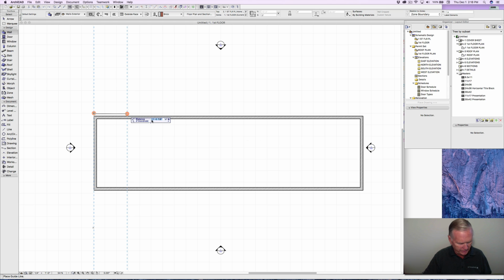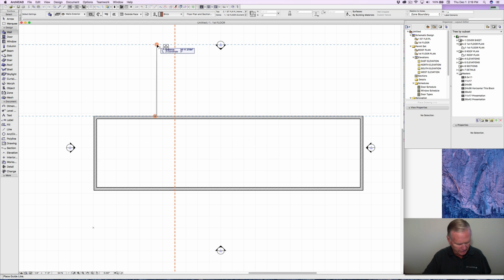And we're going to put in the distance there of 28 feet because that's where we want that guideline. And again, just 28 is needed. Okay, and then we're going to be up here 24 feet. Again, highlight, find the guideline dot, drag it up, hit D as we're dragging, and just type in 24, enter.